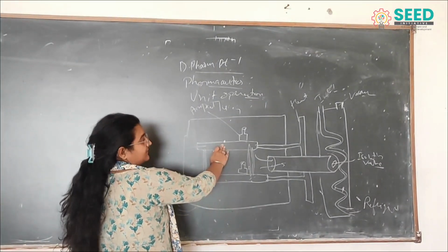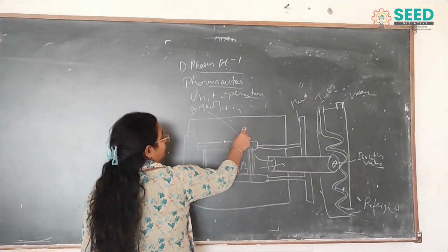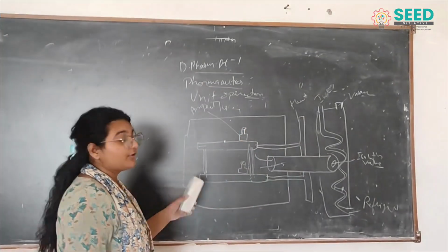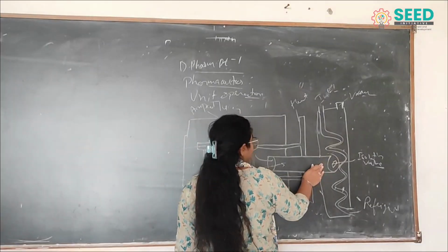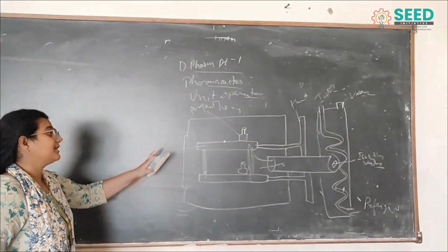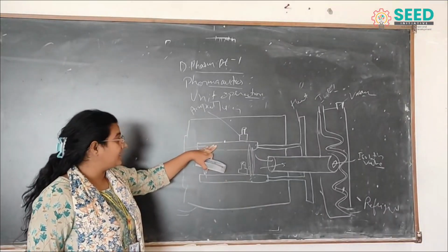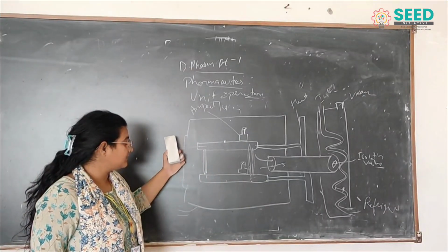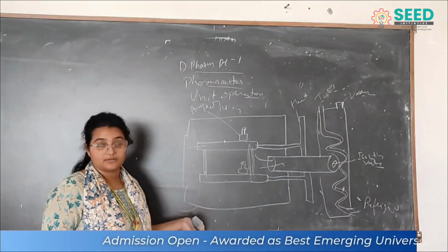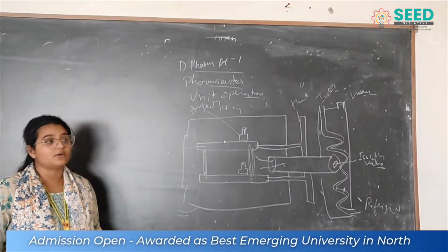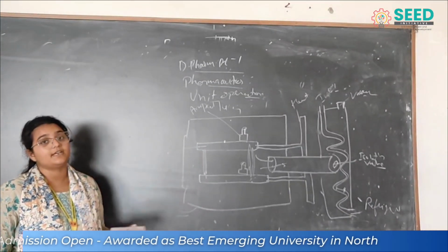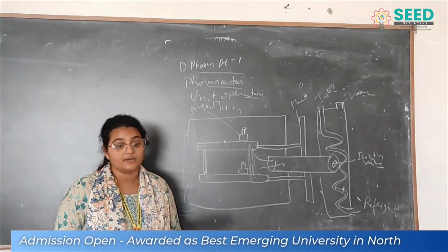These are the key steps. First, we manage the vacuum using the vacuum and isolation pump. We maintain the pressure, then freeze these bottles, apply the heat and continue our drying with the process we just talked about, and then we get the freeze-dried concentrate.